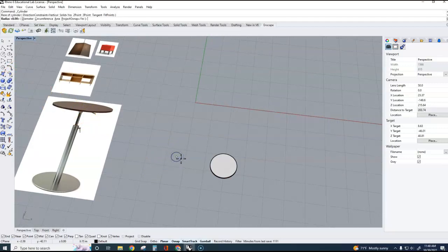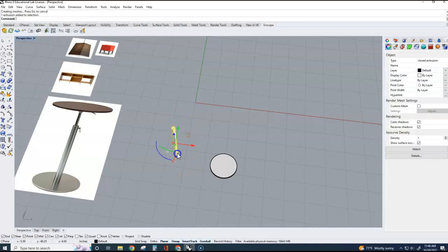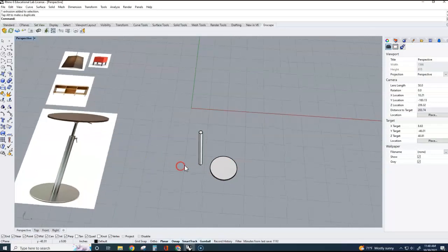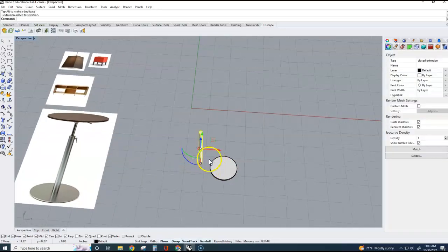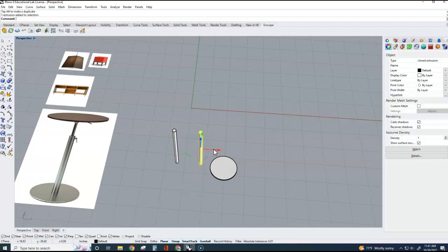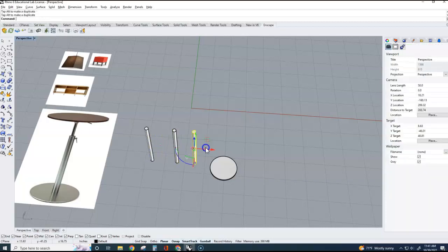That tube is probably about a 1 inch or 2 inch diameter, and it's quite long. So we've made two primitive shapes, right? Cylinders. If I want to make this guy here, I could do it again, or I can copy this. So I'm going to select it, hold down Alt, and then click one of these arrows, and that makes a copy. So do not click the arrow and then hold down Alt, because it won't do anything. You want to hold down Alt first, click the arrow, and then drag it, and it'll make a copy.